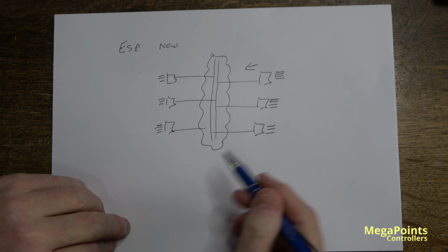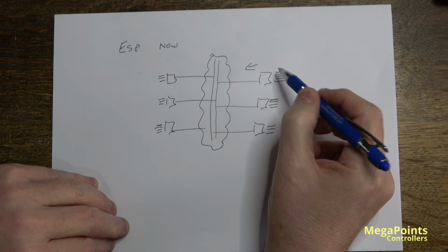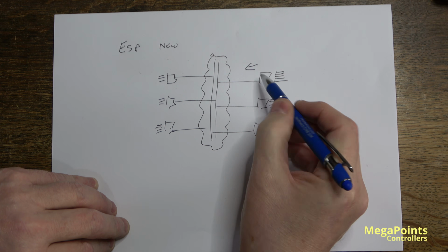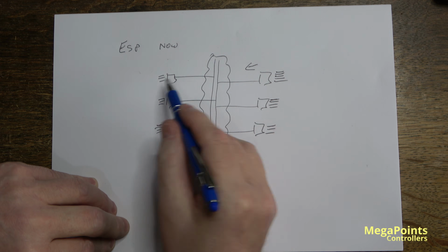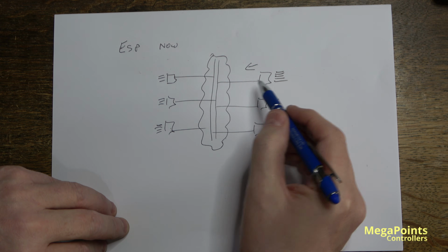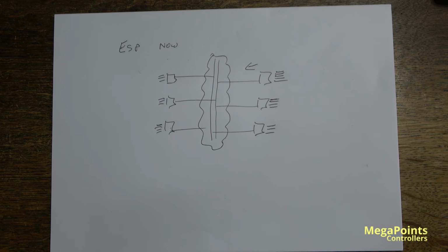So it will transmit it, and because there's a list of, in this case, 5 other boards here, it will drop down the list one at a time, and it will transmit that data on an individual basis to that board, and then it will get an acknowledgement, then to this board, then to this board, then to this board, then to this board. And because we're no longer a broadcast network where we just put something on and it goes everywhere, we're having to manually take control of that. Suddenly the overhead of that protocol is quite high. It's quite an expensive protocol.